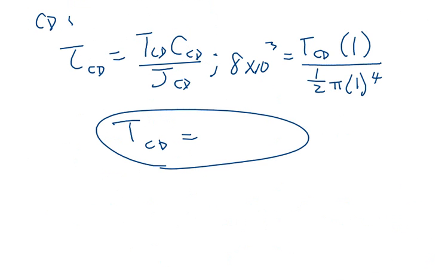You know that because C and B are connected by those gears, torque CD is actually RC over RB times torque AB. It actually gets multiplied.